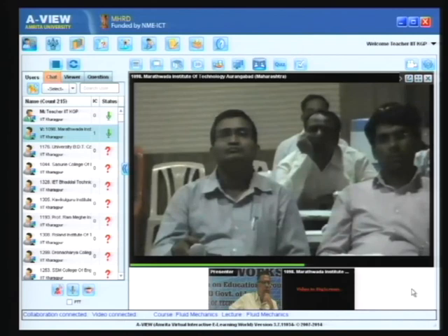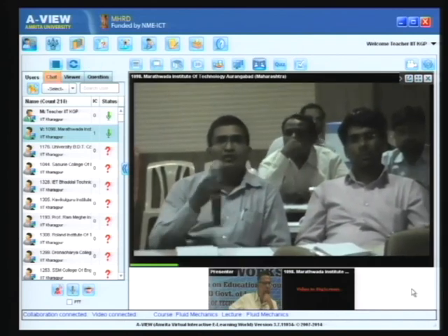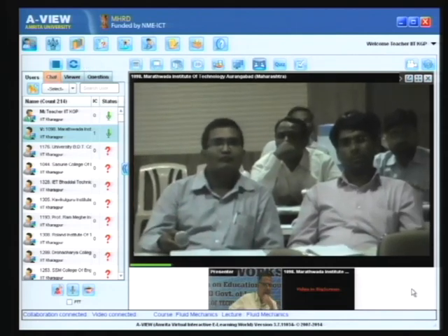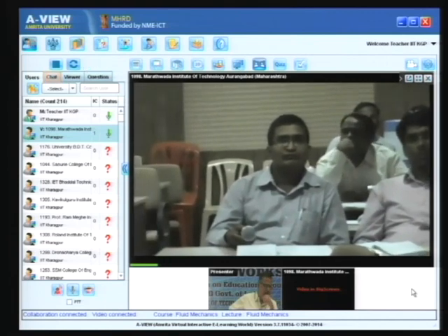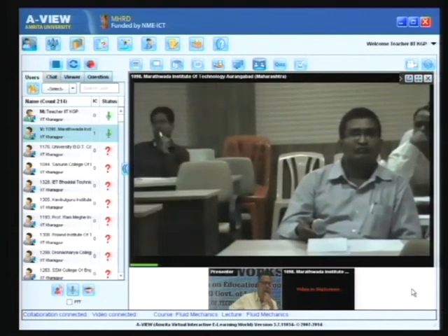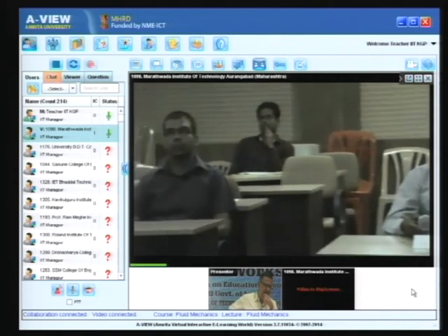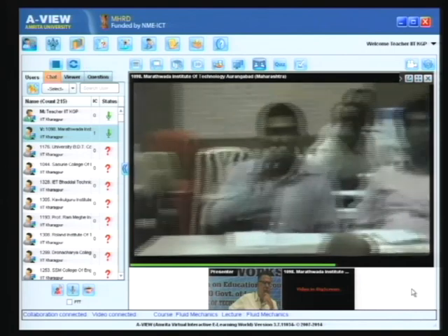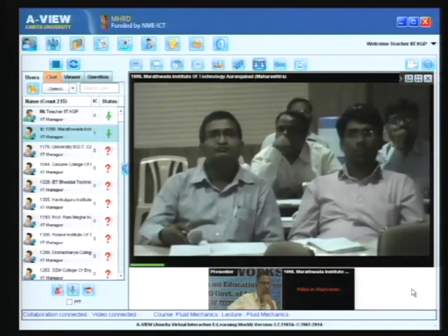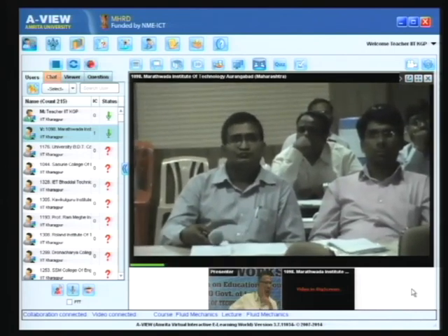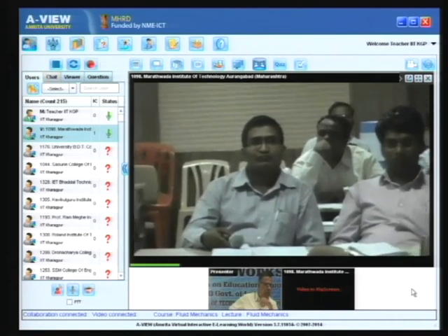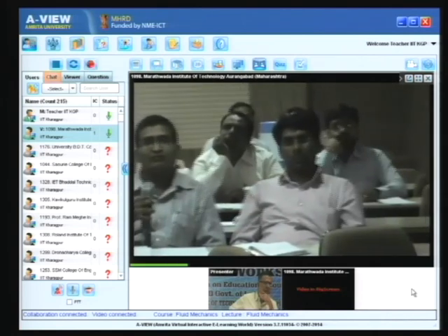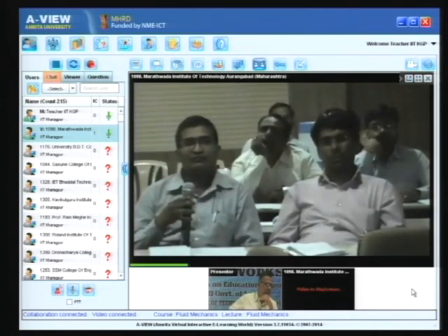See, the form which we have used is a compact form, using which we derived the expression for the force on an inclined surface in about 2 or 3 lines. Now that form is valid for any coordinate system. For the inclined surface, I did not take z to be vertically upwards. The z was perpendicular to the plane surface, and the plane surface was described by z equal to 0. So that is convenient.